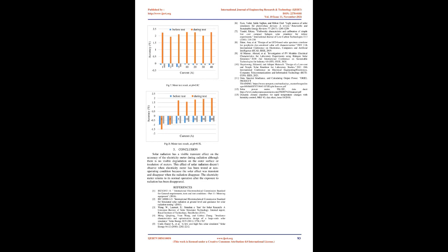After the standard test, the electricity meter was tested at the operating condition with the same environmental values, then the accuracy was measured before, during, and after exposure to solar radiation. Table 2 shows the accuracy results in 3 cases. Figures 6, 7, 8 show the accuracy of the energy meter under different loads for each case. Table 2: accuracy test result for the electricity meter in 3 cases.